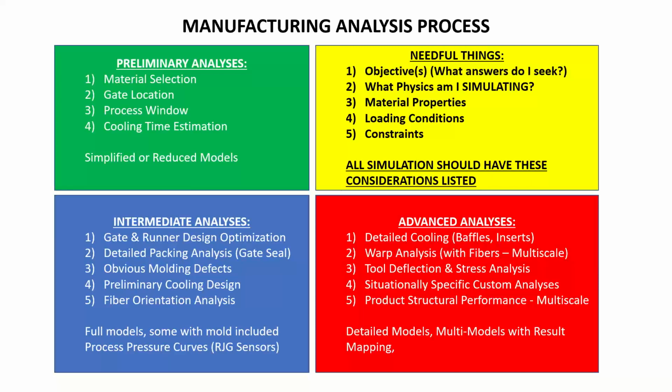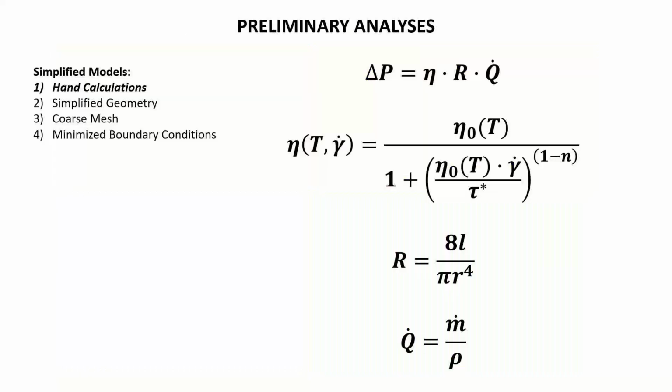Plus, you might get into product structural analysis. Maybe you need to initialize the part with some information like the fiber orientation tensor, in order to get a detailed structural analysis or performance analysis of that part. That becomes an important thing: to really do your analysis homework up front so that you're doing fewer simulations later. That's how we make ourselves cost effective as analysts.